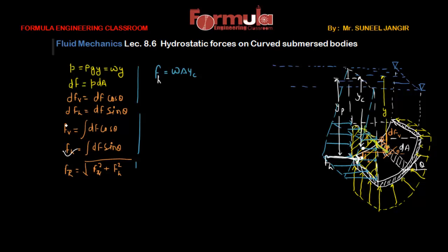Now to calculate the vertical force, we have to calculate the weight of water above this curved surface. Let me draw it again here. It will take a little bit of time, but the diagram is consistent, so I am drawing it again.